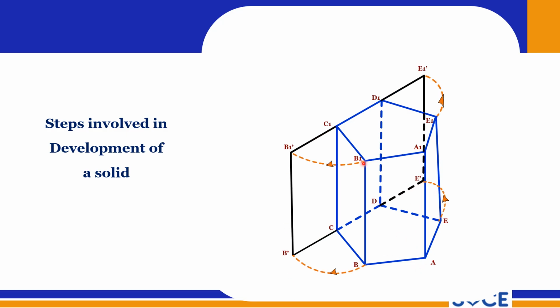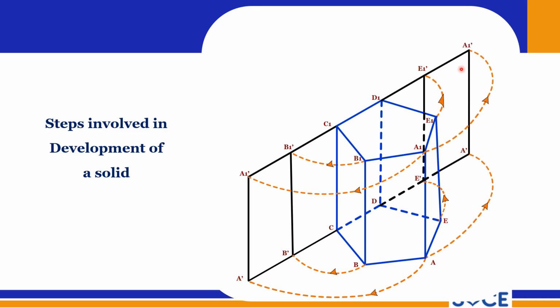So first I have unfolded the first face which is attached to this reference face, and then this side also I have opened it, and now the left out face is this, and this is unfolded in this direction, and this side we have one more face that should be unfolded in this direction. So this is the direction of unfolding. So no need to draw these arrows and all. If you unfold this and keep it on the plane surface, that gives you the complete development.